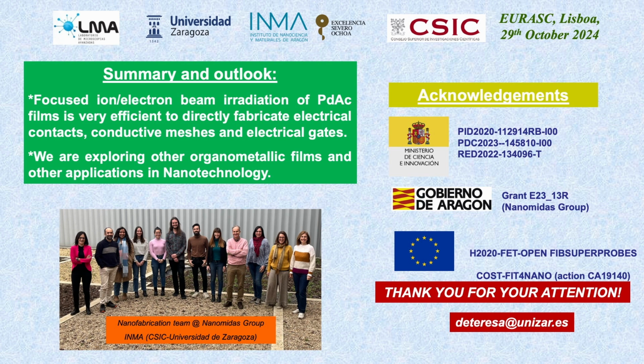This is the summary. I hope I have convinced you that the use of focused ion and electron beam irradiation of palladium acetate organometallic films is very efficient in order to directly fabricate electrical contacts and electrical gates. And we are now exploring other organometallic films and other applications.